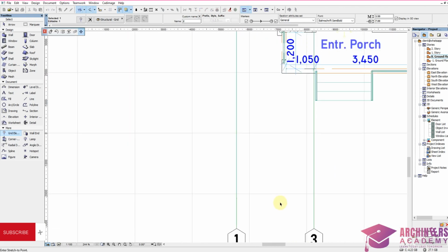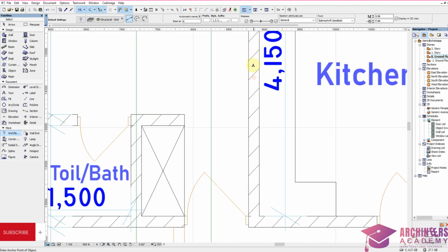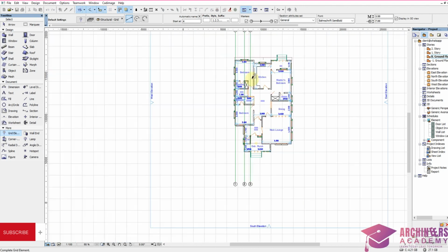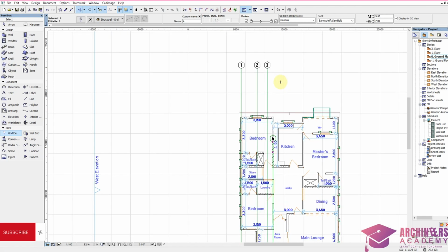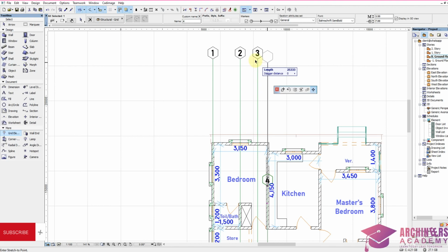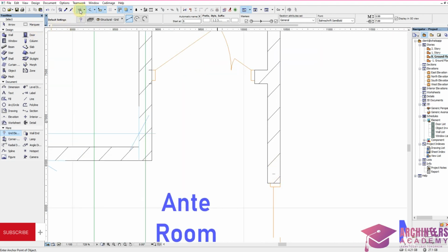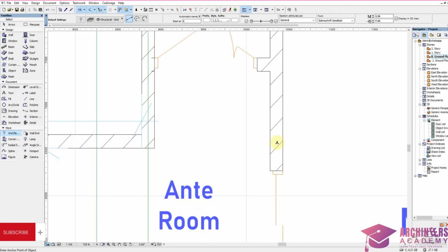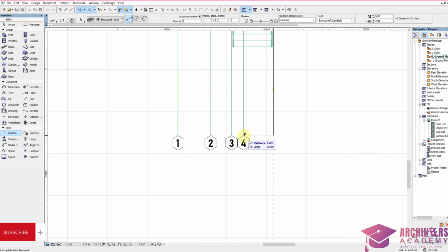So move on to the next one, which is 4. We'll just get the center point there. If your grid is on center, the construction method is center, and these center lines of directions are not showing, endeavor to make sure that your guideline is on, your special snap point is on, and also your show tracker is on. So I'll move on to the next one, which is 5. It automatically generates it.